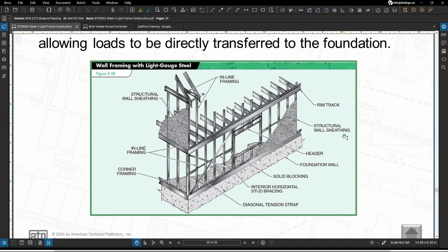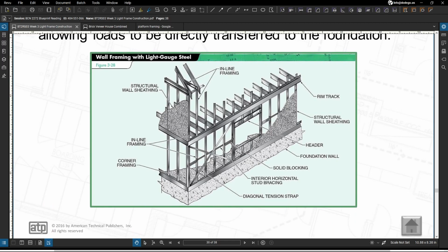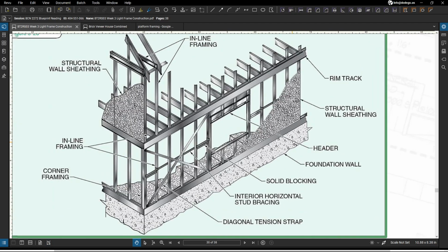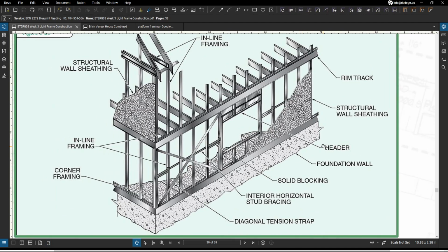exterior walls, which are placed on the floor joists and the subfloor, we're going to take a little look at, okay? So your exterior walls, which consist of your load-bearing studs, often referred to as heavy gauge framing members, with top and bottom tracks. So your solid C shapes or your C shapes with knockouts punched in the webs are used as your studs. And studs with knockouts allow the passage of plumbing pipes or electrical conduit.